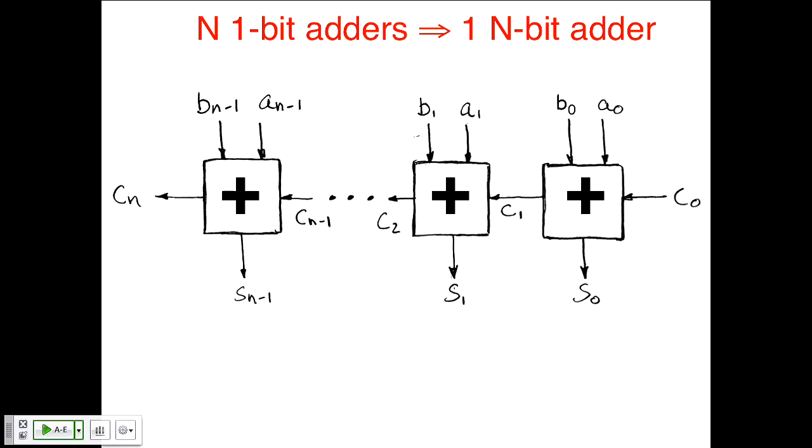And just think about what happens in a circuit if you build a circuit this way. Say I present all the inputs at the same point in time, A0 through A3, B0 through B3. What's going to happen is the signals are going to propagate through those blocks combinationally. They're just going to ripple through.